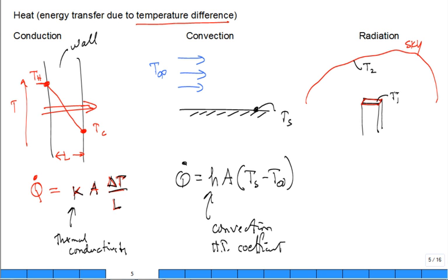And this rate of heat transfer is given by Q dot is equal to an emissivity of the top of the plate, that's a property of the top of the building, times the area of the top of the plate or building times a Stefan-Boltzmann constant. It's like pi. It's just a constant, but it has units. It's not dimensionless. It's Stefan-Boltzmann constant times temperature 1 to the 4th power minus temperature 2 to the 4th power.